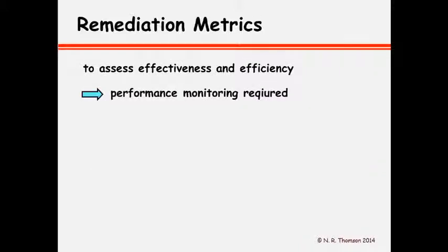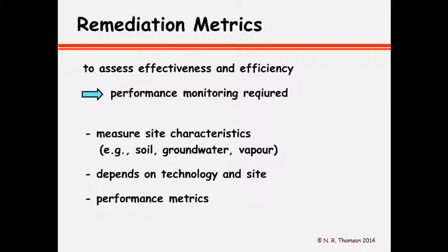With regard to metrics, they are actually the performance data collected at a site to assess the effectiveness and the efficiency of a site. So that requires performance monitoring at the site, where you actually measure specific site characteristics, perhaps groundwater, gas phase, and soil. And of course, that depends on the technology and the site. And those data that are collected then comprise the performance metrics of the site to get at the objectives of the cleanup effort.